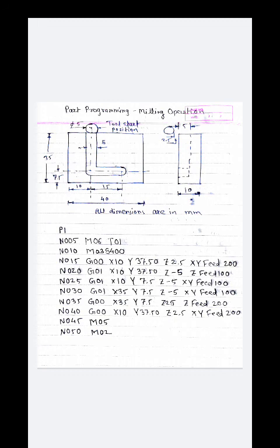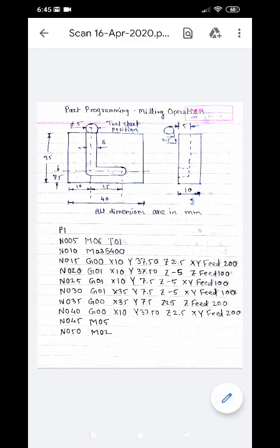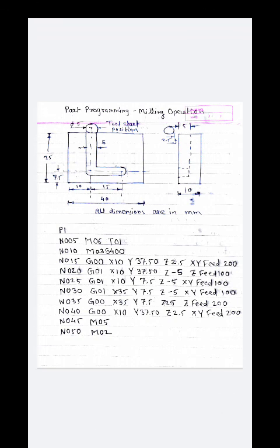Okay, so I forgot one more thing that I said earlier, that I have taken initially the 5 mm depth. So you can take a 1 mm depth, and you can repeat it again 4 times. Initially the first cut with 1 mm, and the remaining 4 times the 1 mm cut. So total 5 cuts of 1 mm, so the total material removed is 5 mm. Okay, that is, the total depth is 5 mm.